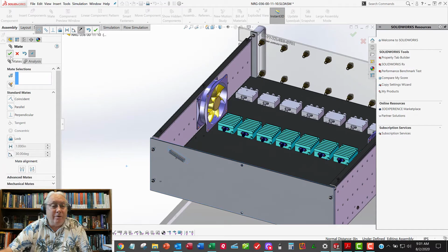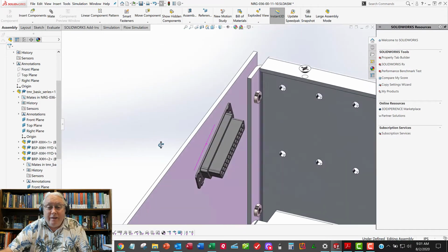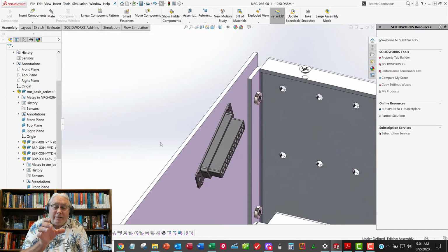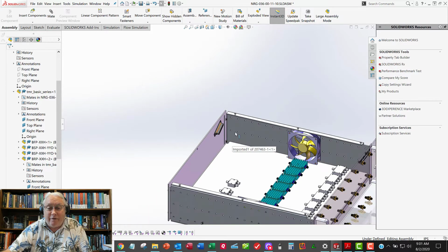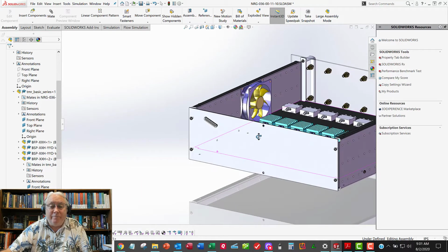So I think that's what I want. Yes, it is. It's going to stick through that way. That way, when the connector needs to be replaced, there's going to be pins, there's going to be wires coming out of this thing, 25 of them, connecting to our dash 50 DIN rail and to who knows what. And so we need to make sure that we can pull this thing out from the inside. So that's why it's called a rear panel mount.